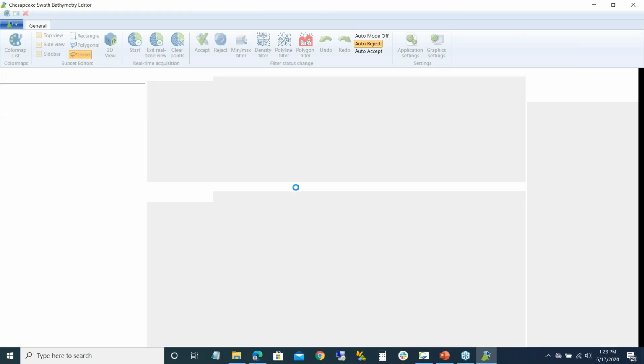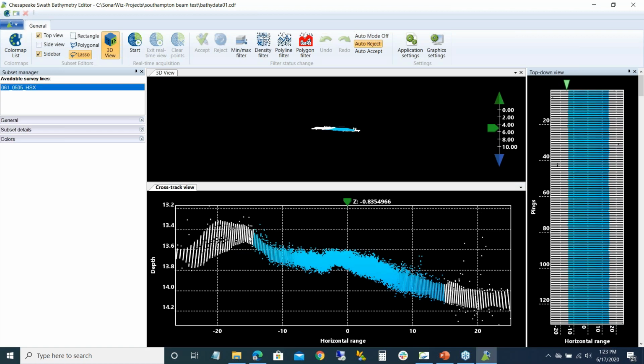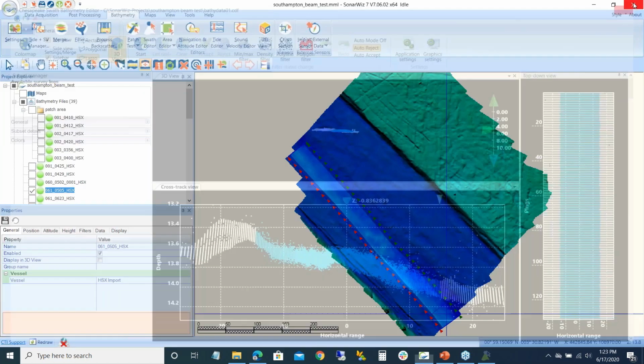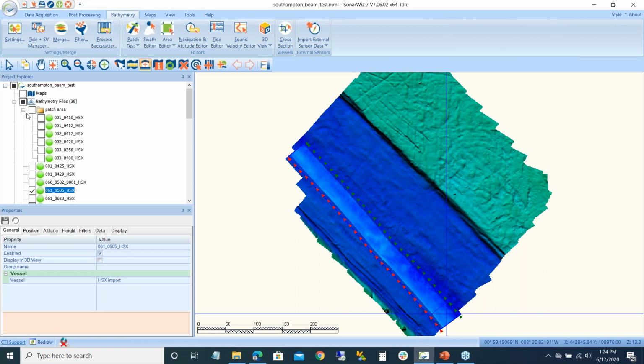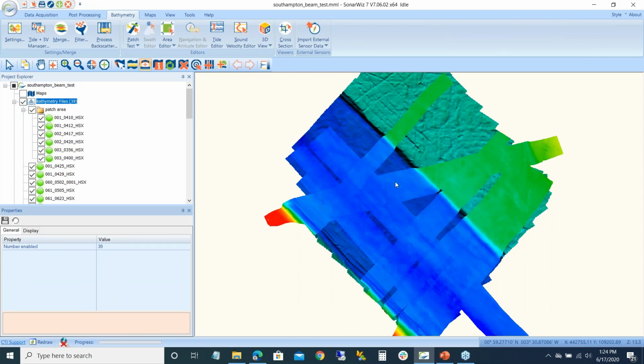And the point is, we want to get rid of everything outside of 45 degrees. If you wanted to use 50 degrees, you can. If you oversampled it more, you can use 35 degrees. But you can see that this data has been deleted out or rejected out. So we have a really tight Bathy grid. And you saw from before, that's what my data looks like.